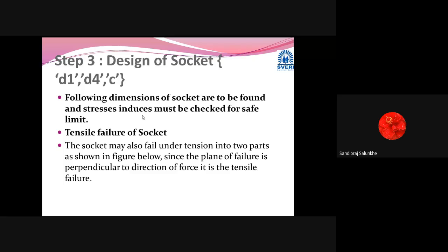We are going to calculate allowable tensile stress, allowable shear stress, allowable crushing stress, allowable compression stress from the material which has been allotted to us. That material's properties, that is its yield strength and ultimate tensile strength, we are going to know first, and later on we are going to calculate the design stresses and check whether they are within the limit or not.